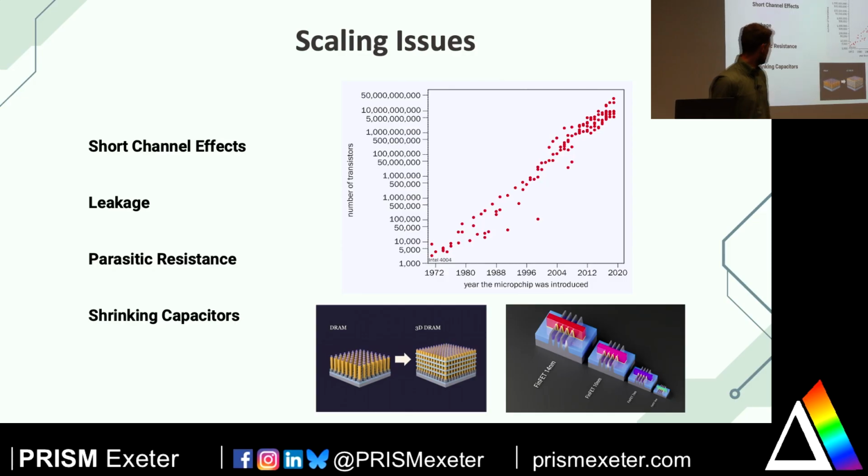So yeah, when we're getting small enough, for example, you're getting currents flowing through these devices when you don't want them to be and they're not meant to be. And all sorts of other problems, like the barrier that you need to overcome to get them to operate is becoming more and more reduced. And another example is in the DRAM earlier, when that's getting smaller and smaller, it's harder to store any charge in the capacitor. So there's a lot of challenges that need to be overcome.